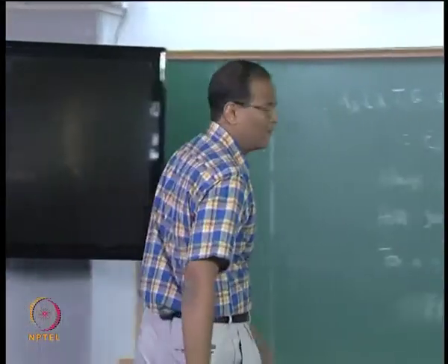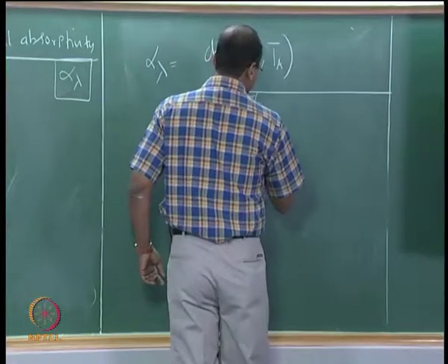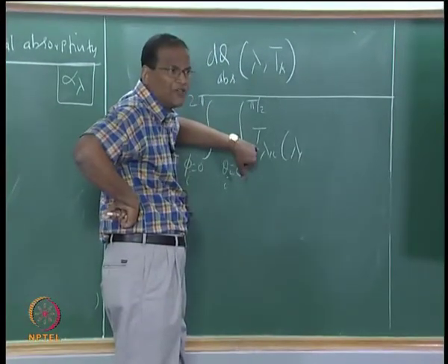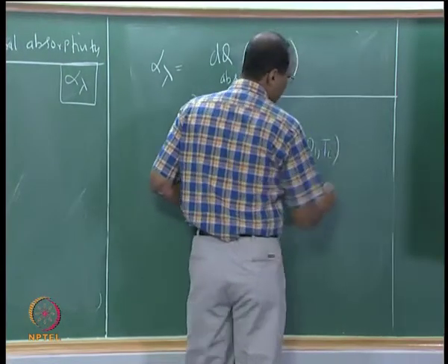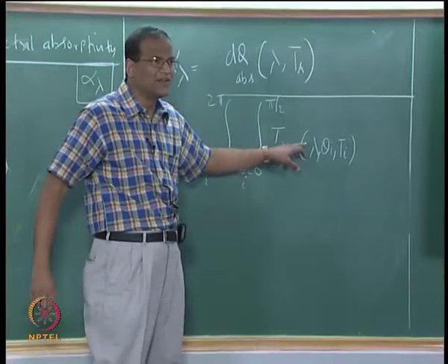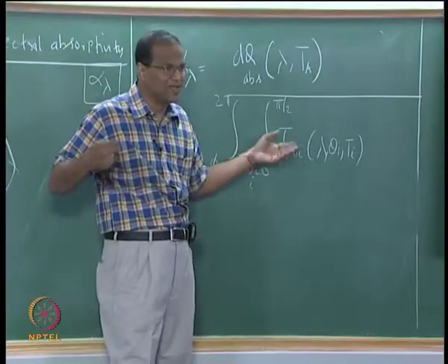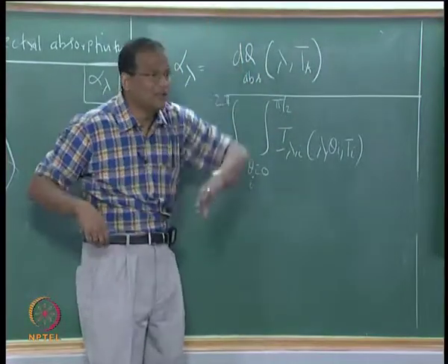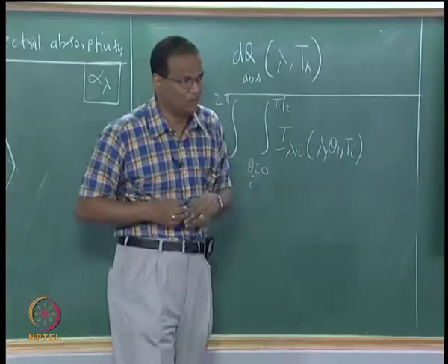I lambda I, the incident radiation could be a function of lambda, it could be a function of direction. I do not have to write the temperature if I know what this I lambda I is. Only in the case of incident radiation from sun I need to write the temperature, because if I know the temperature of the sun I can assume it to be a black body.